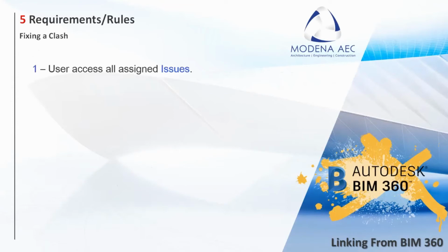So the first rule is that users access all assigned issues. As a user, you would need a document management license in order to select all the issues that are currently under your name or assigned to your user email address. Number 2 is that we adjust all necessary clashes in Revit. Remember, Revit is the authoring tool that we are building our model from, not BIM 360. BIM 360 is just a point to view, critique, comment, and mark up specific models.